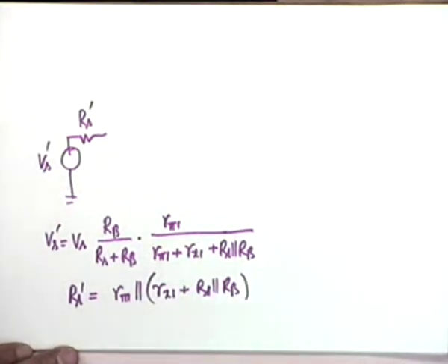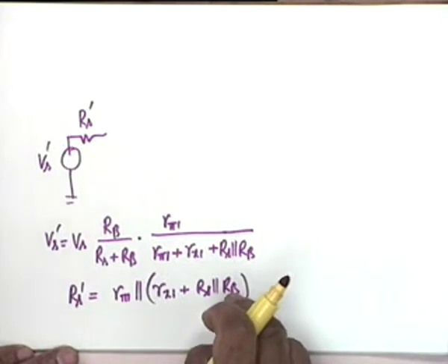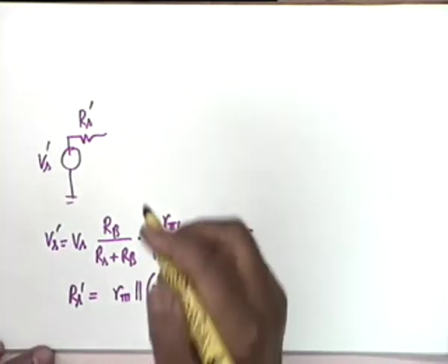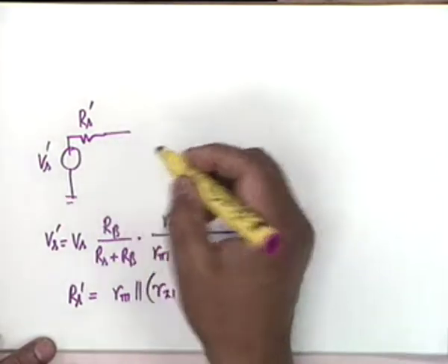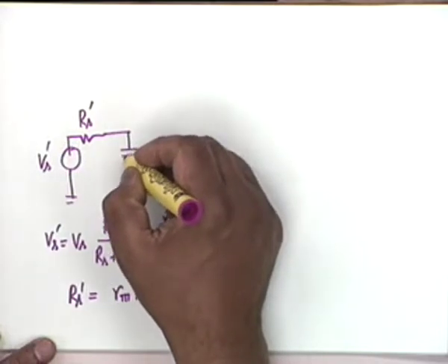Okay, a two step circuit being considered, being written down by inspection. Is the point clear how this comes at as the equivalent resistance? This is the Thevenin equivalent of the first step that comes in series with Rx1, and the whole thing comes in parallel with R pi 1. So this is the first simplification. Then R pi 1 has been absorbed in Rs prime, so I have a C pi 1.